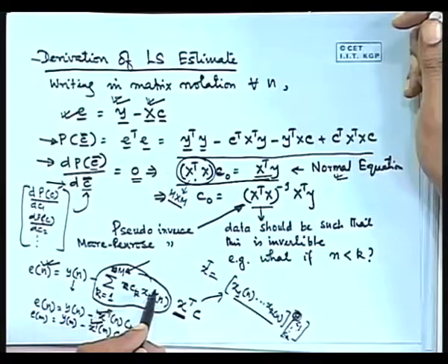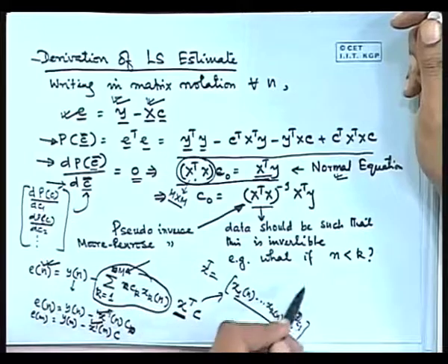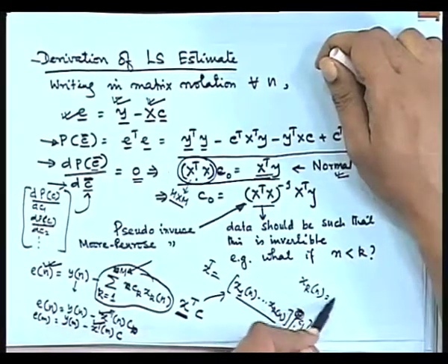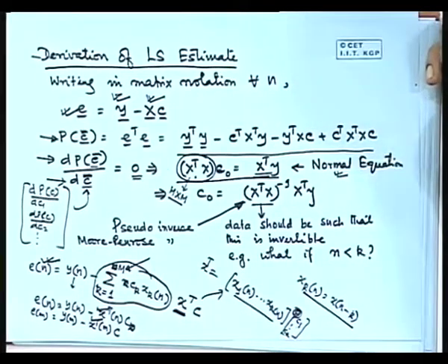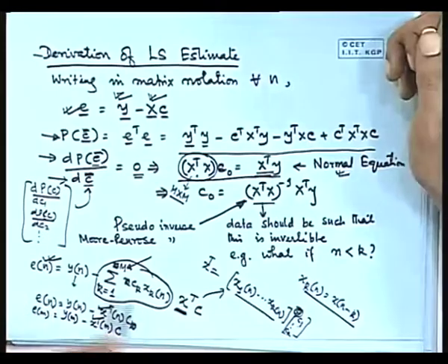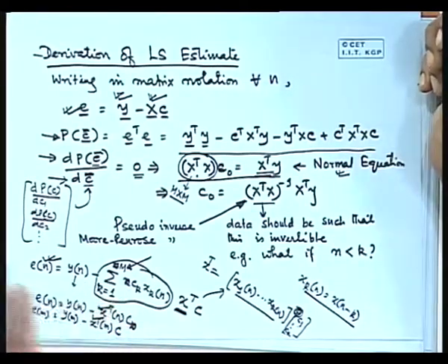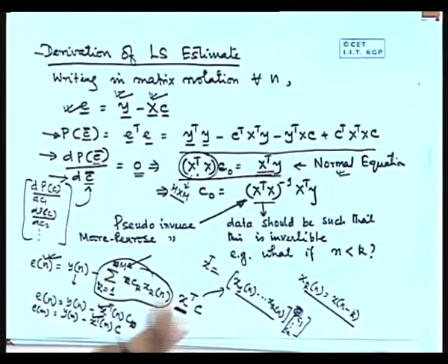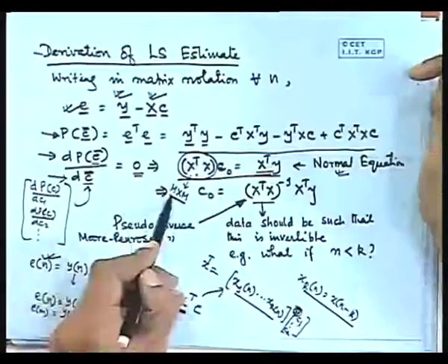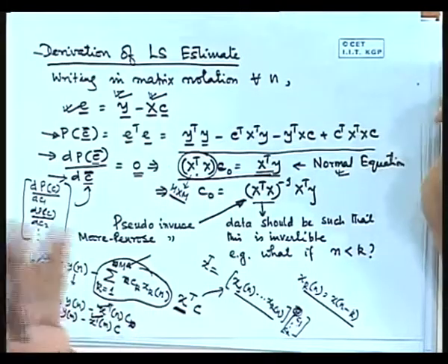See, when you are doing an FIR, why I say FIR, because this is a very general description. You can always write that xk(n) is equal to x(n minus k). You can always define xk(n) in that way. Then it will become a true FIR filtering. Now I'm saying FIR filter, but it's not. It's actually as if data is coming from capital M different sensors, and we are making them sum. This equation looks like that. So it's an M into M matrix. It is square, but we don't know whether it's invertible.